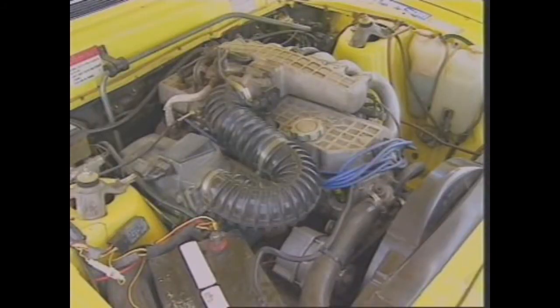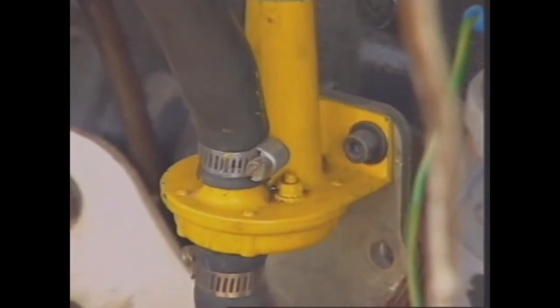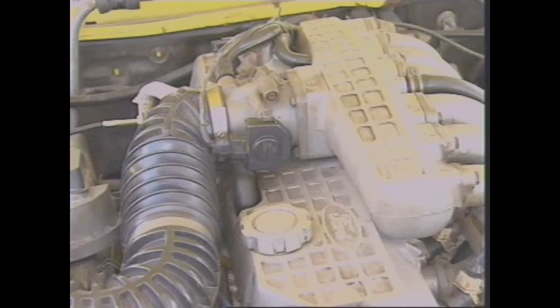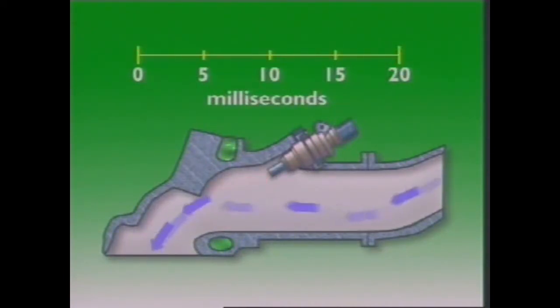The extra air needed for a cold engine can come from an auxiliary air device. This one has a connecting hose from the intake air side to its controlling passageway and a return hose to the plenum chamber. It bypasses the throttle plate when it's in operation to provide the extra air. The control unit reacts to this additional air by metering additional fuel. This makes more air-fuel mixture available during the warm-up period.